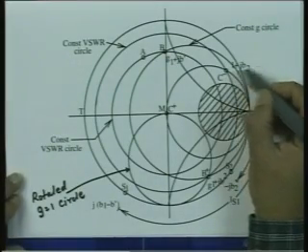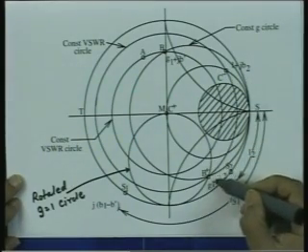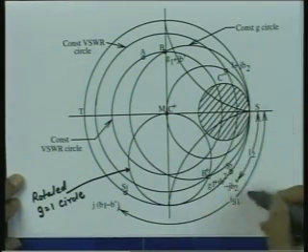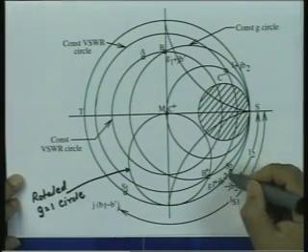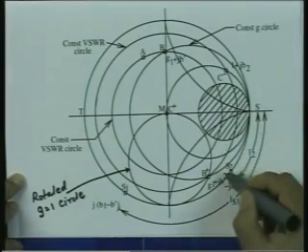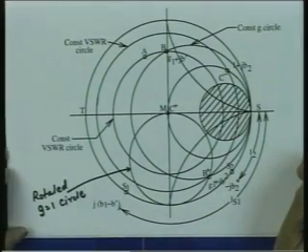Once I get this, I have to cancel JB2, so I take the mirror image of this JB2 and find out which is the mirror image of this point passing through this point, and find out what should be the length of this stub, so that it will give me a susceptance of minus JB2, which is the same as what we have done in the single stub matching.